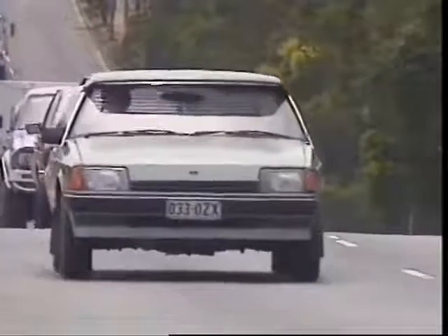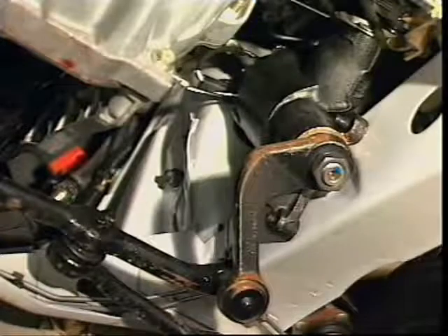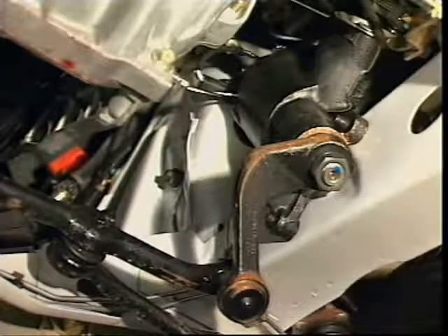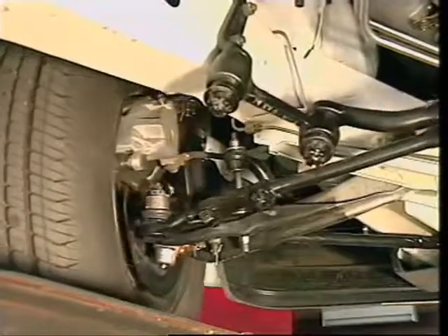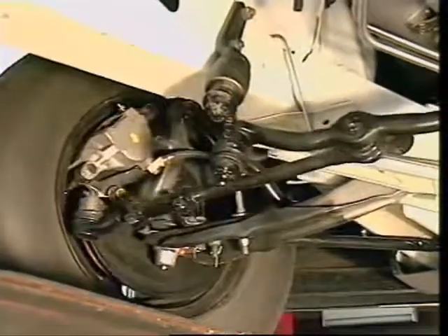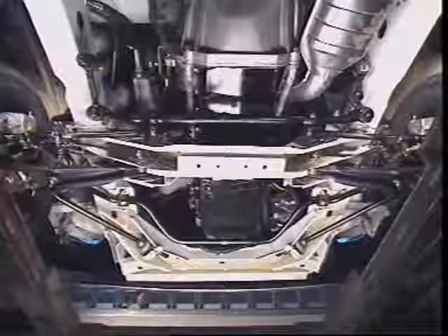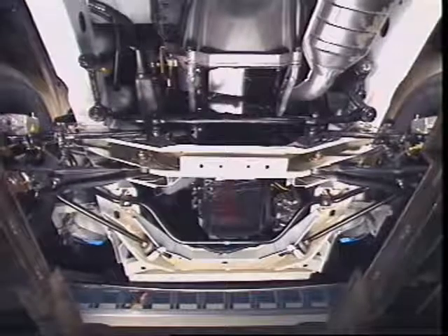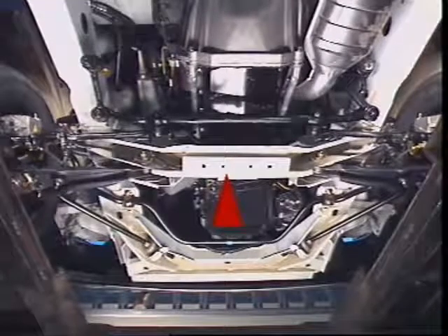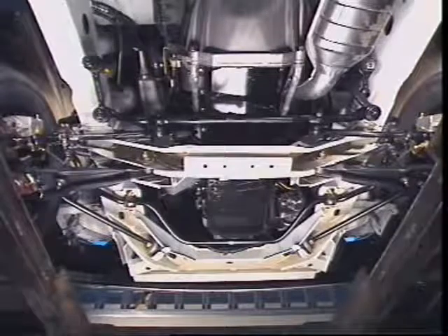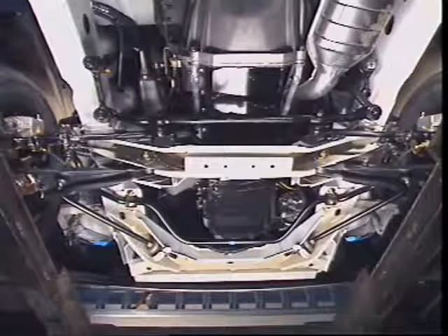Passenger cars with independent suspension and using a worm-type steering box may have the steering box mounted so that the linkage is in front or behind the suspension crossmember. When the linkage is behind, it is protected by the crossmember from possible damage, and the position of the steering box reduces the length of the steering column.